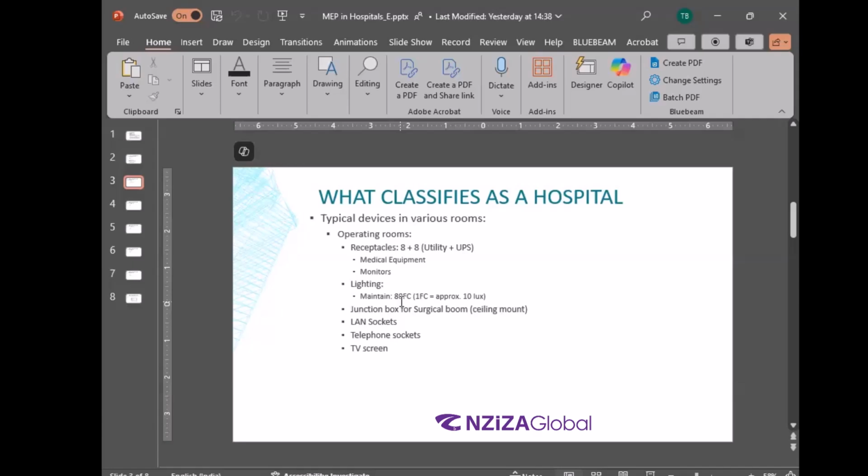Repeat? Sure. So, first of all, we are getting lumens out of every light fixture, right? You add up the lumens throughout the room for every light. Lumen divided by square foot, area in square foot, will give you the foot candle.